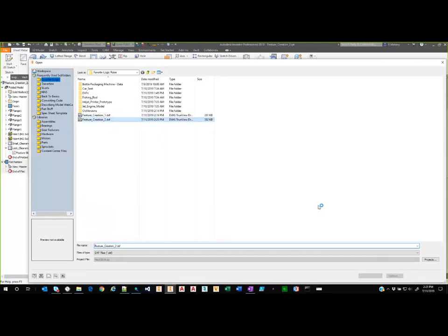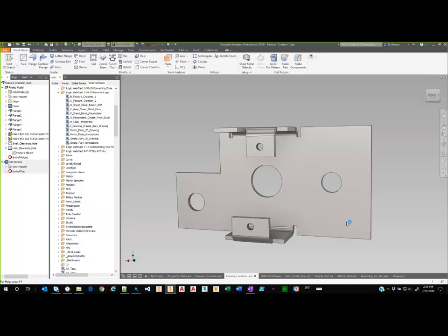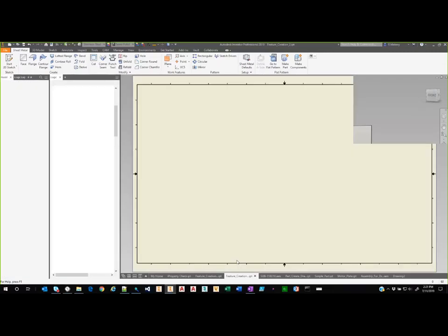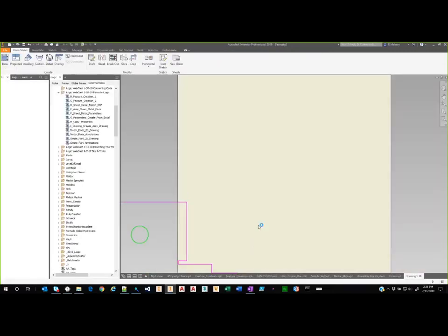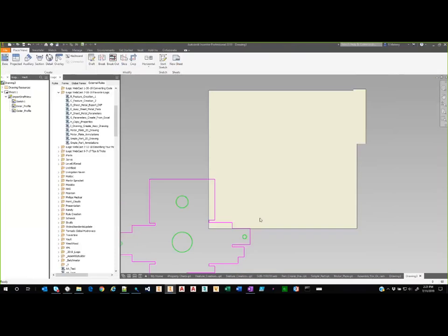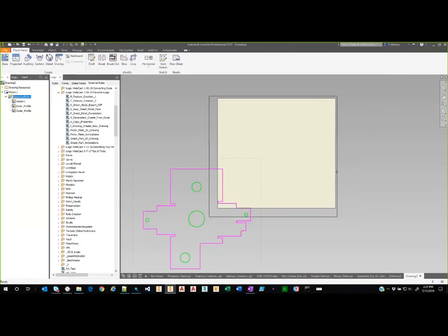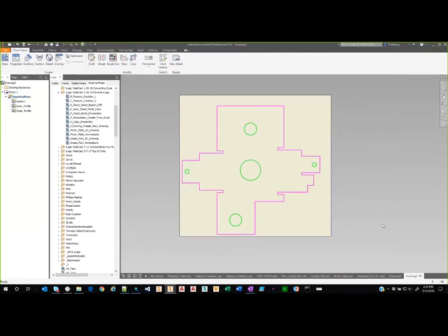Of course, if you're doing something with the Inventor nesting utility, obviously you wouldn't have to be going through this process. You could use it for getting these flat patterns out of it. And then even certain other newer controllers don't even require the use of a DXF either. They could take that native Inventor file. But there's the DXF. Again, I'm doing the same thing there. I'm modifying some of those layers upon export.